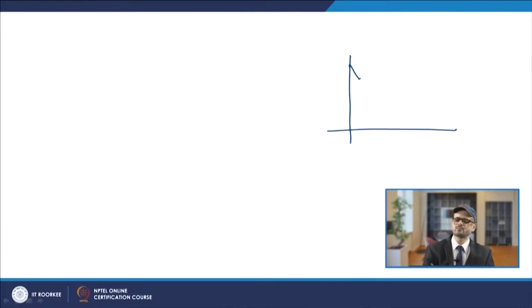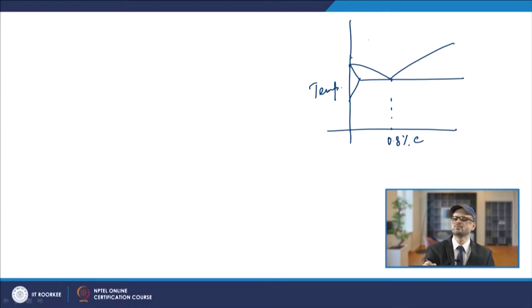First of all you have to go into the austenitic zone. As you know, this is the iron carbon diagram. This is your eutectoid composition, about 0.8% carbon, this is your temperature, and this zone is the austenitic zone. If you talk about this composition, when the temperature comes to this point, it will convert to pearlite in normal cases. Here on this side you have ferrite and on this side cementite, a mixture of ferrite and cementite in alternate lamellae. That is known as pearlite. So, austenite will be changing to pearlite.